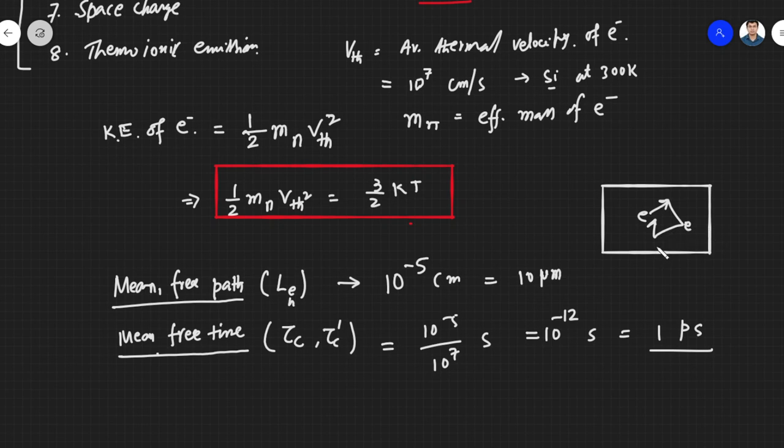Now at thermal equilibrium, they have this random motion, and this is the collision rate, this much they can travel before hitting another collision. In this situation, we don't have any effective current because it's random motion. With equal numbers of electrons and holes, if you take a time average over a cross section, it will be 0. The net charge flow will be 0, so there is no current flow.